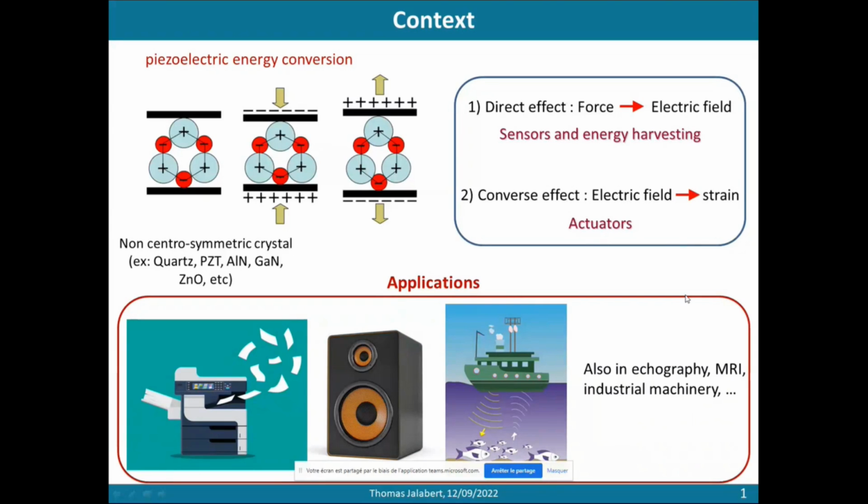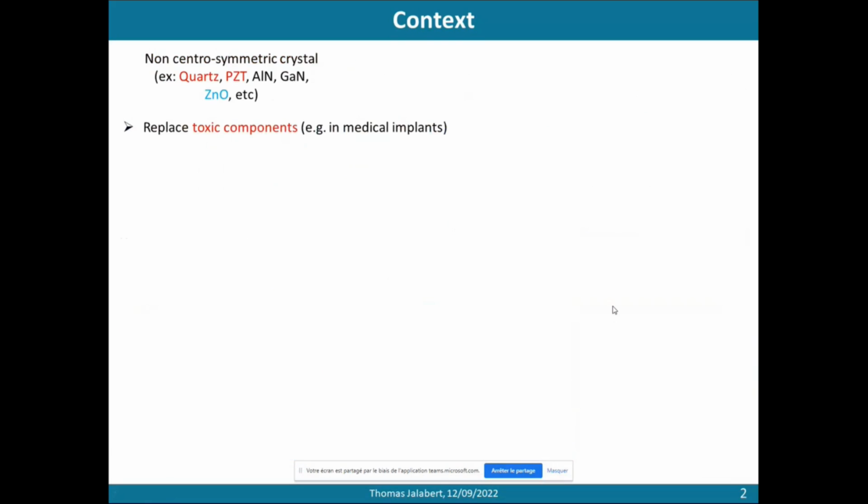Also, because we need quite a large voltage to result in a relatively small deformation, piezoelectric materials are interesting in the industry as actuators to induce small displacements with high accuracy. As researchers, we don't only look for materials with the largest piezoelectric properties, but we also want to replace the toxic components, because one piezoelectric material which is widely used is PZT, which is based on lead. So it's a toxic material, and it's an issue for medical applications.